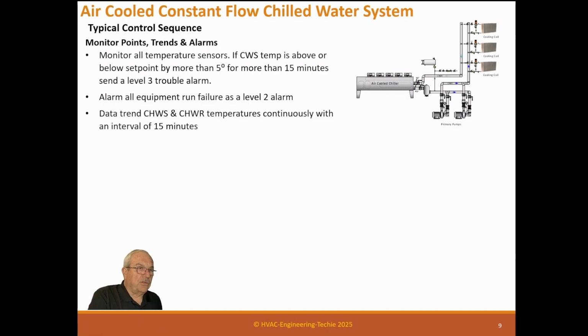Data trend chilled water supply and chilled water return temperature continuously with an interval of 15 minutes. This gives an operator a tool to be able to look at what's going on in his system. It's way too long a period to do real diagnostics, but it's going to give you a hint of what's going on and you can get a general idea.